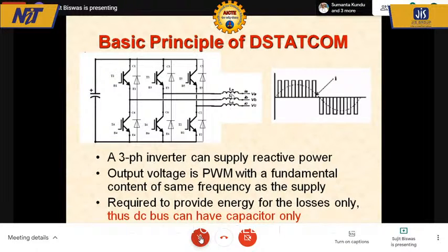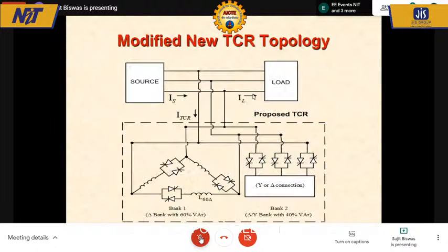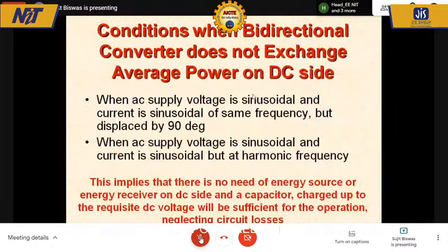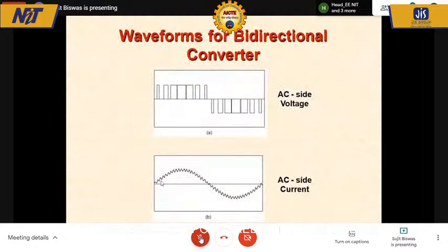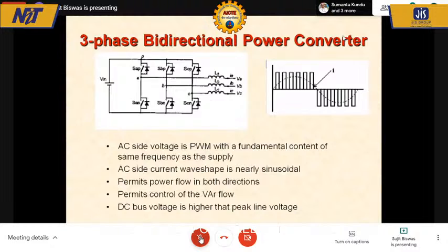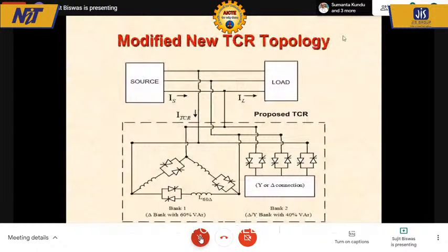So I think it is clear the current flowing out will not be a sine wave anymore, depending on what I had shown earlier for the generalized converter that I had discussed. Yes, this will be the nature of current flowing out. It's not a pure sine wave anymore. It does have harmonics. So there will be some problem coming up with those harmonics.